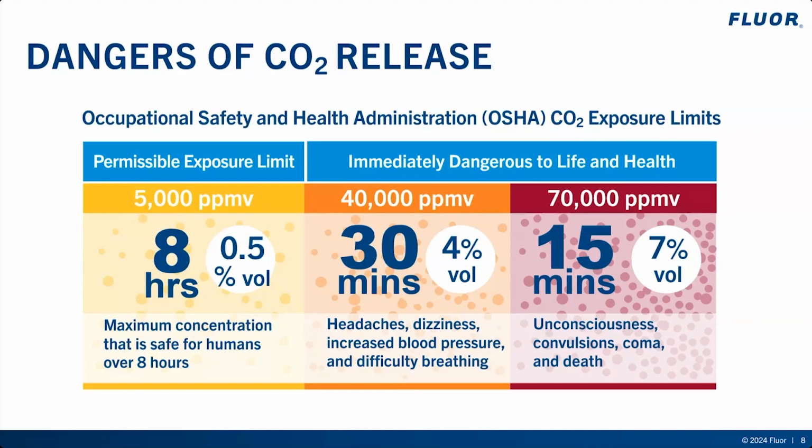Then there's the IDLH, or the immediately dangerous to life and health limit. This is 40,000 ppmv, or 4 volume percent after 30 minutes. It can cause headaches, dizziness, increased blood pressure, and difficulty breathing. And anything greater than 70,000 ppmv, or 7 volume percent, can cause unconsciousness, convulsions, coma, and death.